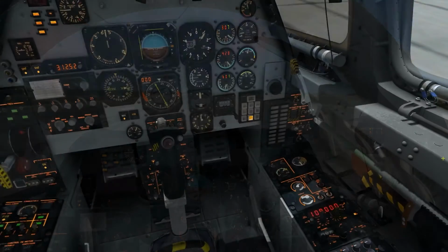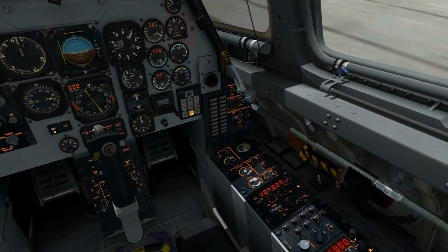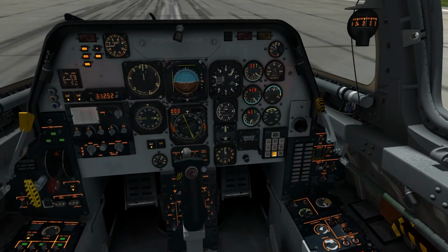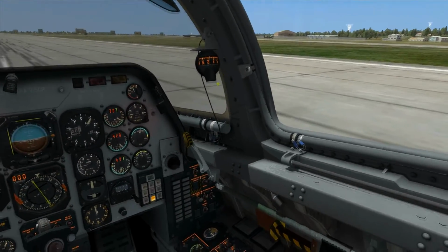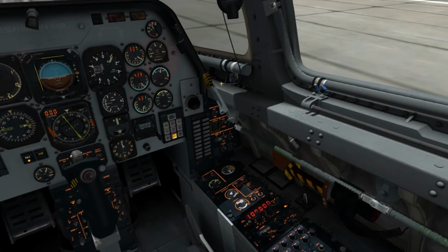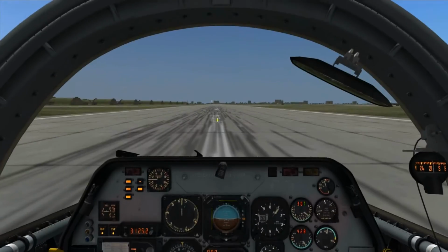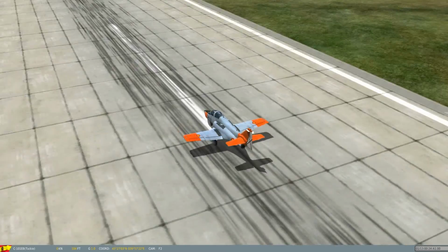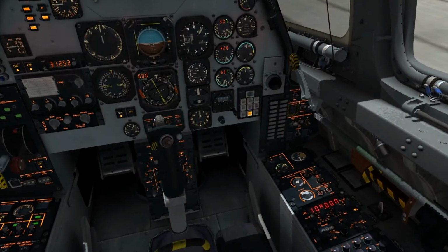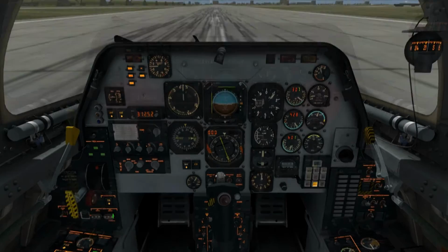Here we are. Lineup checklist. ID test 0, 0 and 0. I assume it means it's not deviating, so same indicating, and same indication. Compass, cross check runway heading. We have not the numbers of the runway. It is curious. This runway has not numbers. Anti-ice as required. I leave it off. There are no expected icing conditions.